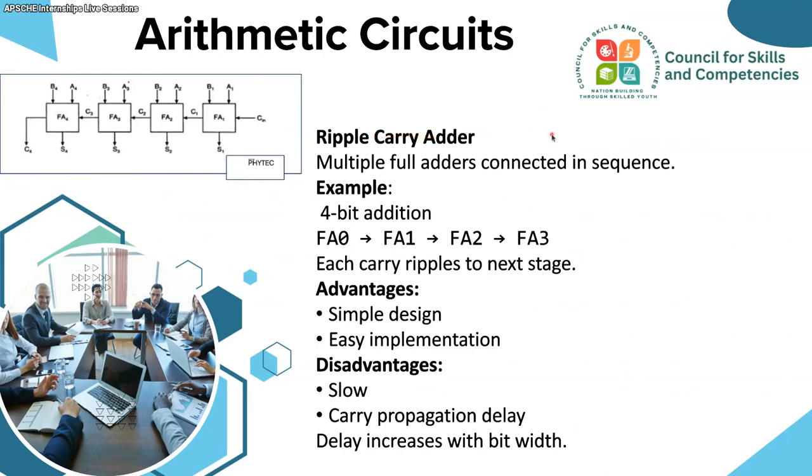so now we want to connect. See, one full adder, when we connect it with other full adders, with the help of these we can do 4-bit addition, with one carry in. Because one full adder gets 3 inputs and you will get one sum.